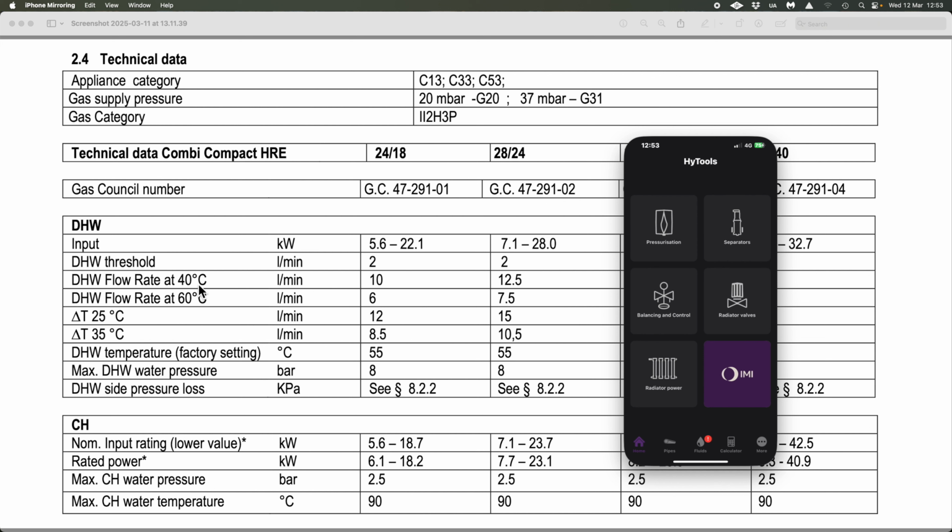Now, be very careful, because 45 degrees coming out of your taps, if you're elderly, can scald you, and could scald children. This is why RAS state 38 degrees coming out of a tap. But a lot of people like to run baths and all sorts of things through combination boilers, so they want it hotter, and then they'll blend it down to suit their own personal taste. That's just a little caveat. This is not a regulatory video at all. This is just purely my opinion.